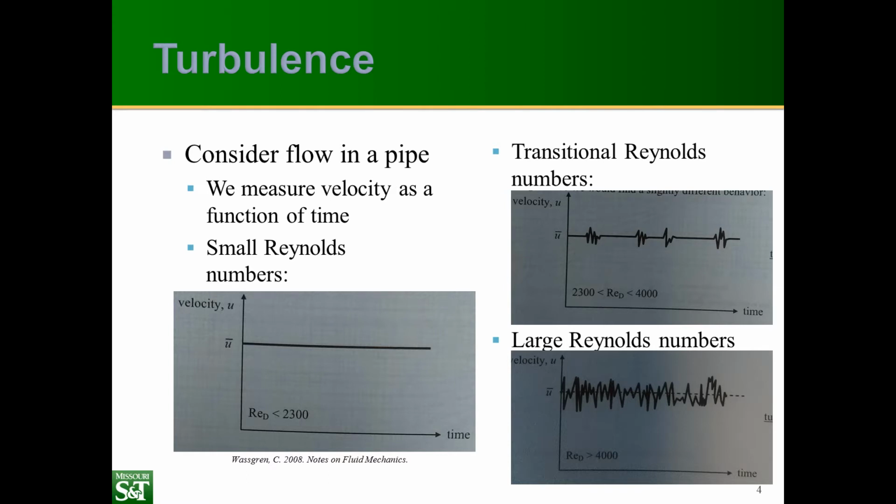So here, laminar flow, Reynolds numbers smaller than 2,300 for flow in pipes, are very smooth. They don't have a lot of fluctuations. Turbulent flow is very complex. The fluctuations are chaotic. They're not random. They're actually governed by chaos theory. But the problem is that they're so chaotic that they're very difficult to analyze. So most of the time, we look at turbulent flows empirically rather than analytically. And so the question becomes, how do we address these turbulent effects in our differential equation for fluid motion?